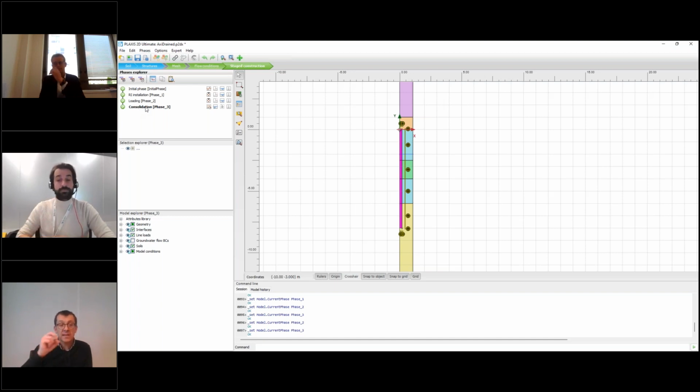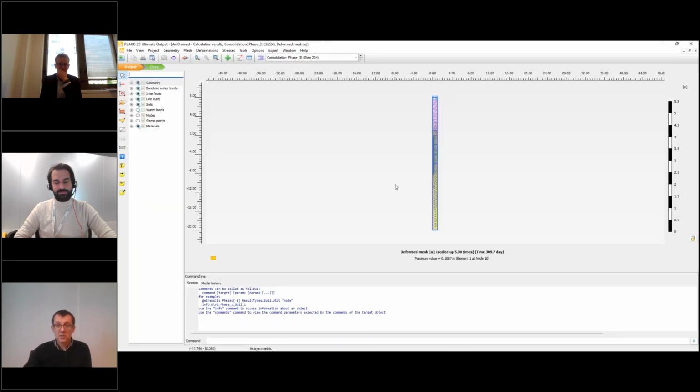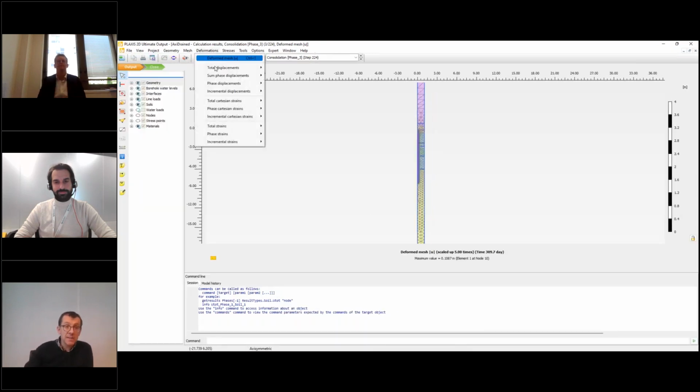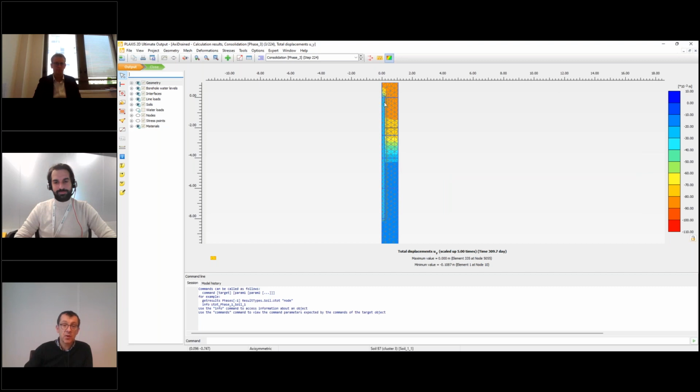And we are doing that calibration exercise based on these long-term results. So once this is done, now we can look at the calculation results, and we will start generating some reference results as Jérôme presented. So this will be vertical displacement, as well as forces that may develop inside the rigid inclusion. And then finally, also take a look at the skin resistance being mobilized along the interfaces.